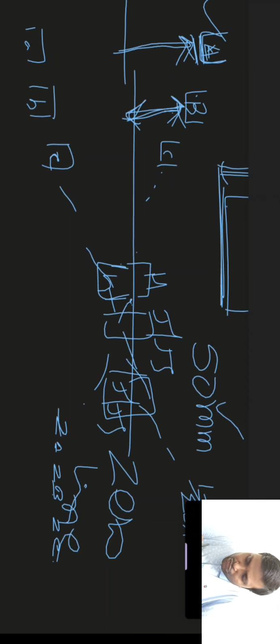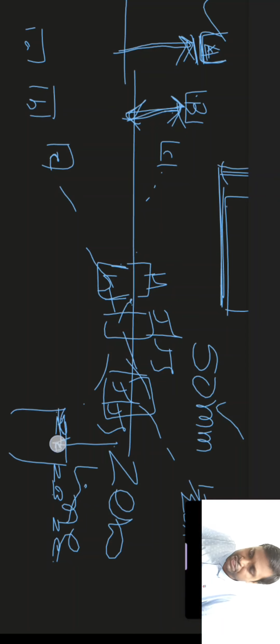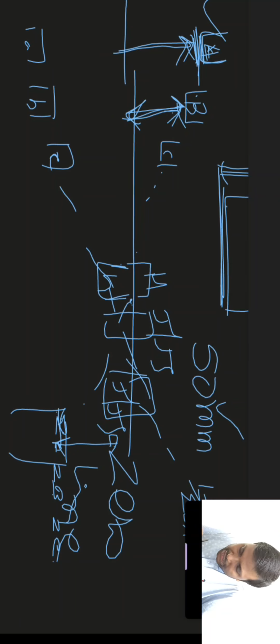And when we move on like this, let's see ZA. So this is the hole. So the fundamental deviation for ZA hole, this deviation is the fundamental deviation for ZA hole, and this will also have a formula. But there is one twist here. The twist is that when we are saying the fundamental deviation of A, this is the lower deviation. But when we are saying the fundamental deviation of ZA, this deviation is the upper deviation.